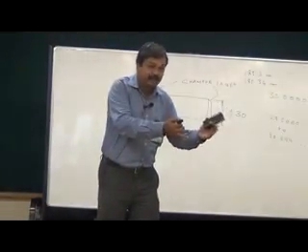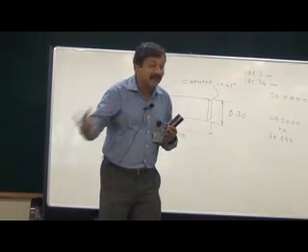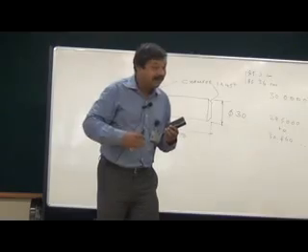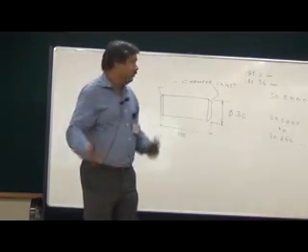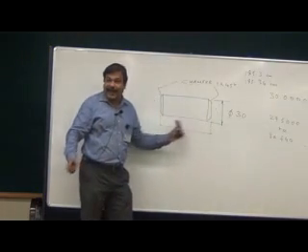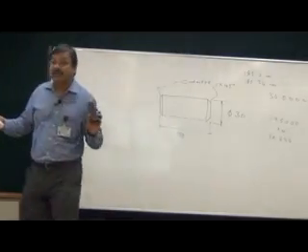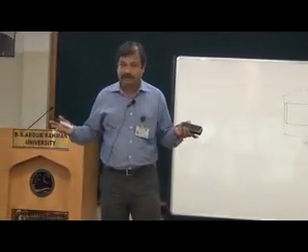I can manufacture a diameter within, say, plus or minus 0.1 mm or plus or minus 0.01 mm. For example, all of you know about the lathe. If I make this diameter in a lathe alone, I can get a maximum of plus or minus 0.1 mm accuracy.